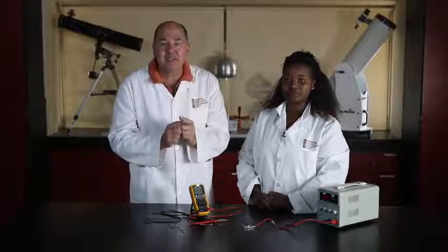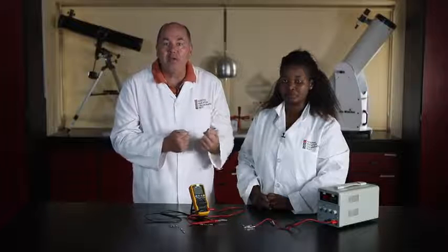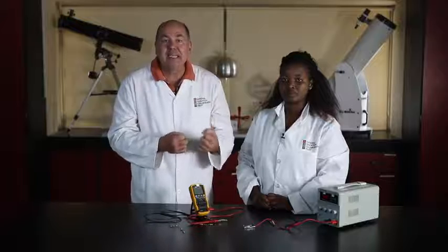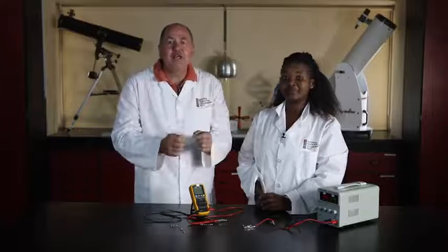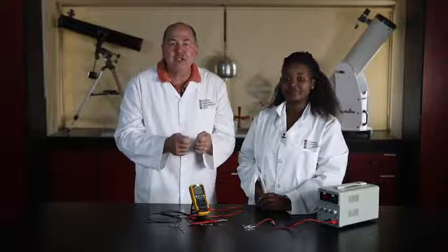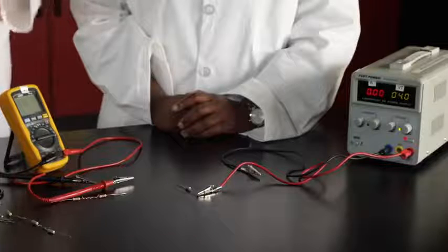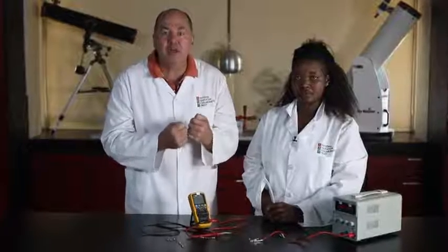The first circuit that we set up is a circuit with one resistor in it so that we can calculate its resistance. The positive terminal is connected to the one end of the resistor and the other end of the resistor is connected to the switch. Well, we don't have a switch here. Yes, I know. I should have said the connection from the resistor acts as a switch. We connect it to the power pack only when we are ready to take the readings on the meters.